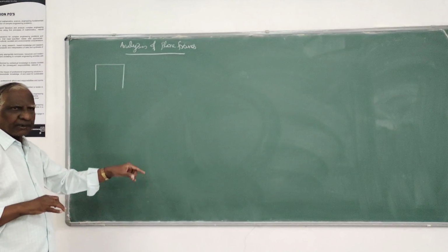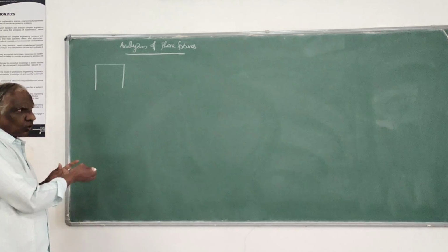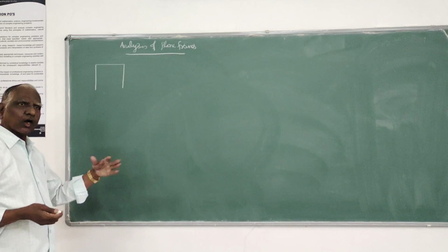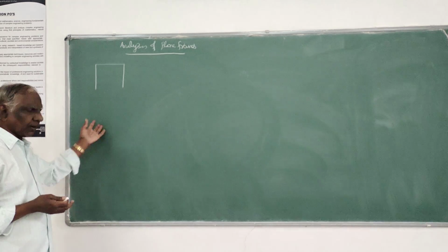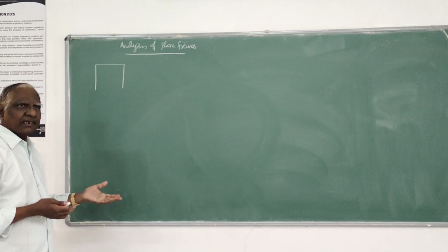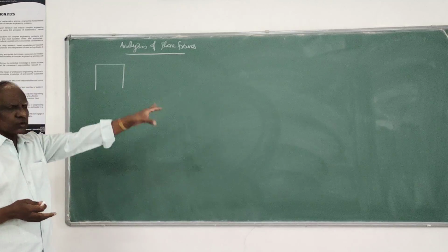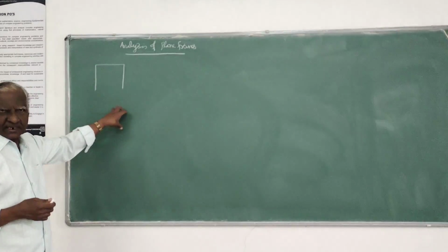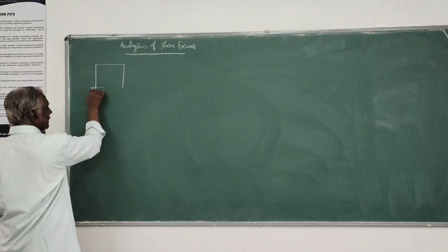Then second step, to find out the displacements along those coordinates chosen, by using standard formula or by dummy load method, whichever is required depending upon the situation. Then third step, you have to generate the flexibility matrix. Then fourth step, use your force displacement relationship to determine the unknown redundants. Those 4 steps remain the same even in the analysis of rigid plane frames also.